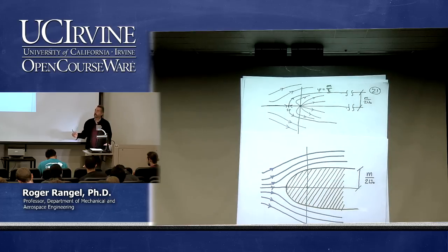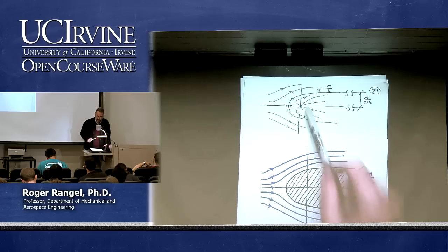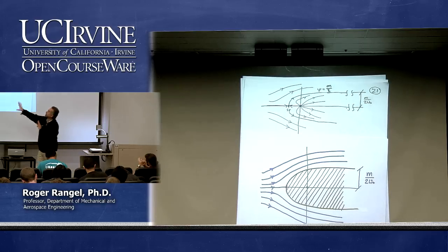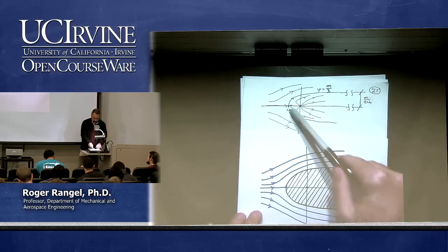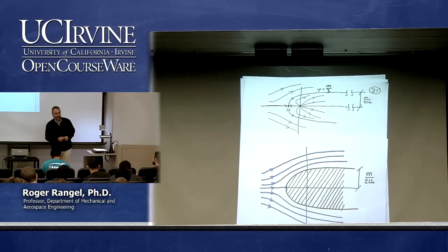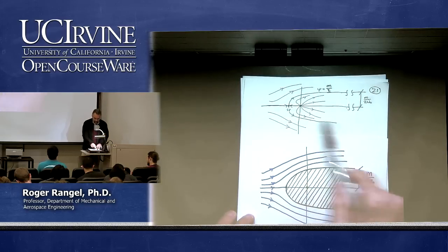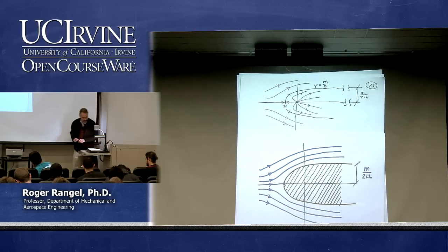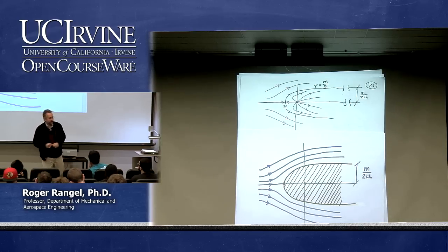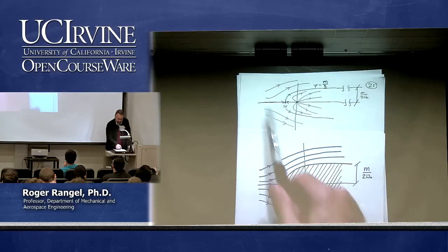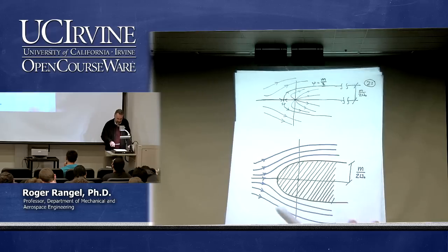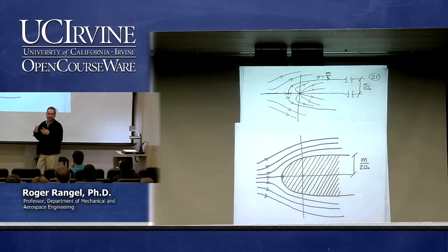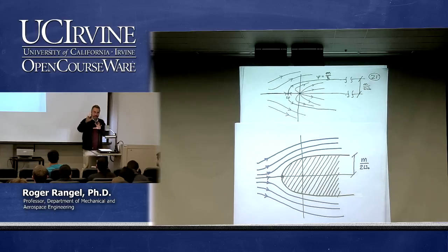So in the top figure, you have the whole flow field. Outside that streamline and inside that streamline. You can see how essentially what is happening is that the uniform flow is like blowing on the source, and making the source streamlines bend like we see in this figure. But the magical thing about this streamline that we just found, and that's what I did in the second plot, where I drew that streamline in a solid curve, is that I can use that to be actually an object. The so-called dividing streamline, which is what we just found, the dividing streamline that came off of the stagnation point is still right here, can be used as the surface of an object that is put in that flow field.